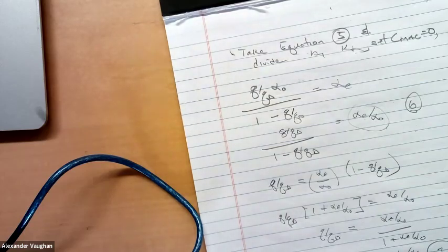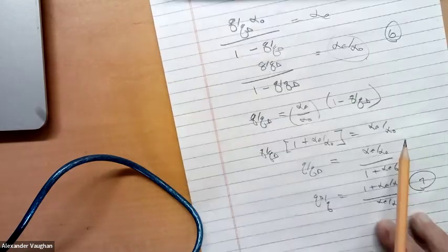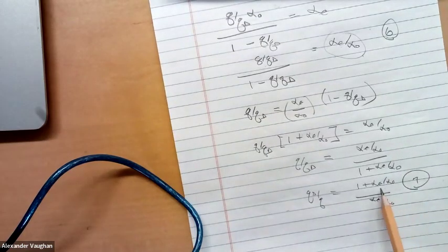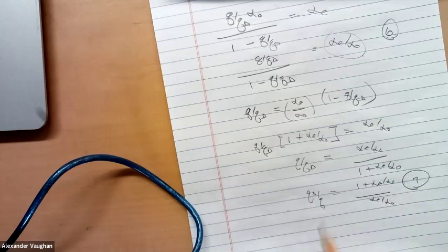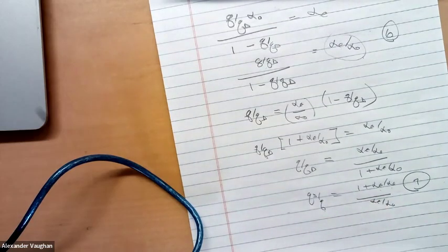Again, why would I want this? Well, let's say again, I'm below the divergence condition. I'm in the wind tunnel. I measure the twist of the wing. So I know alpha E, I know alpha naught. That's what I said originally. And I know at what Q I'm measuring the twist, right? And then I can solve for Q divergence. So by making a measurement below divergence, if I believe this formula, I can estimate Q divergence.